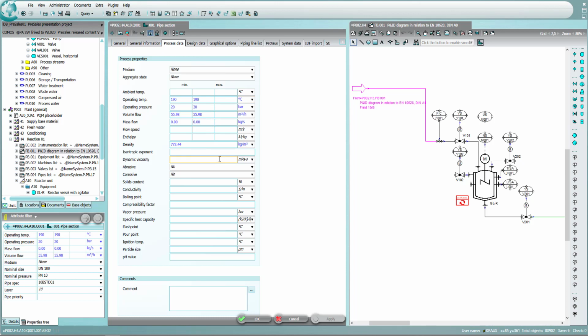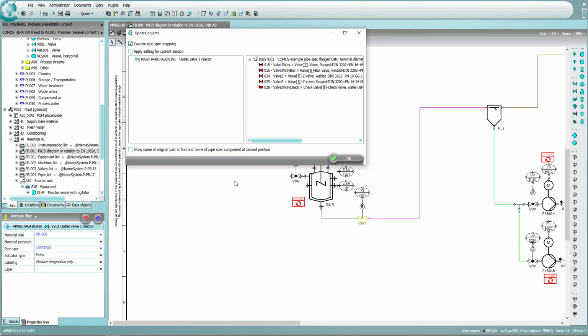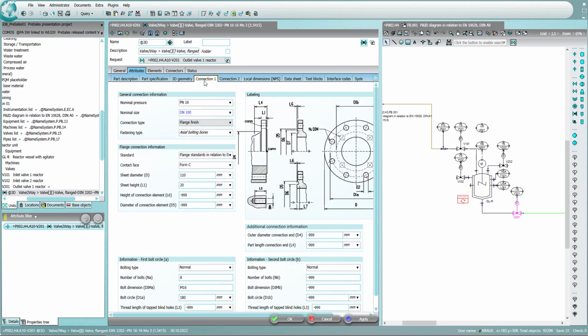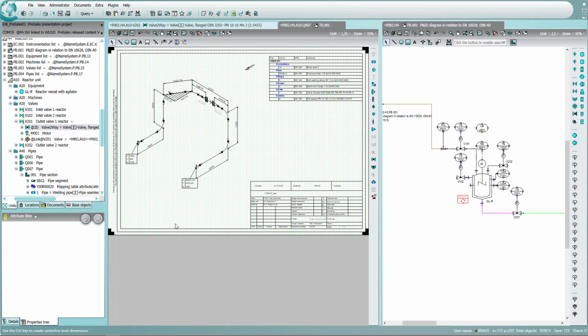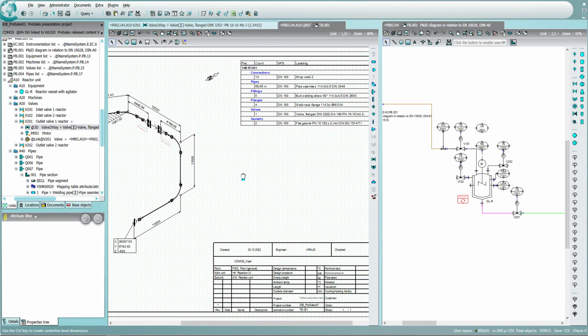Here we find a seamless handover from the imported Aspen data for the min case into the engineering phase, into the basic engineering on our pipe, and further triggering with these routes how the system should now manage all these inline components, creating therefore also for the 3D world geometry data like flange sizes and types. So down to detailed information like the isometric drawing, which is used for manufacturing the piping components.